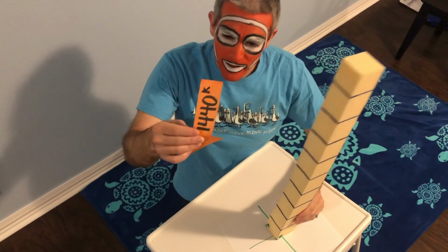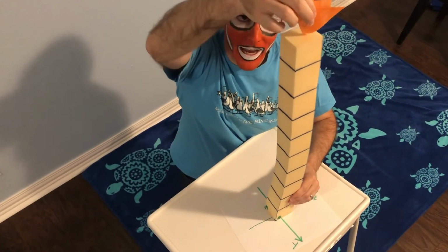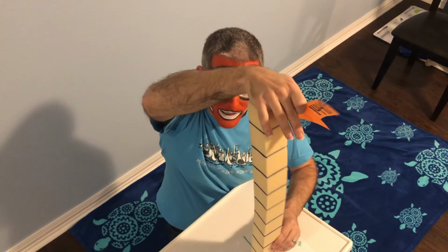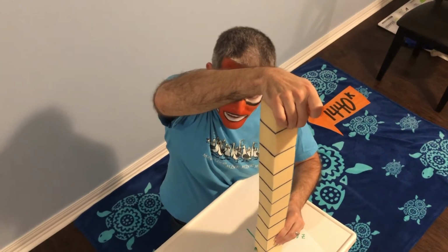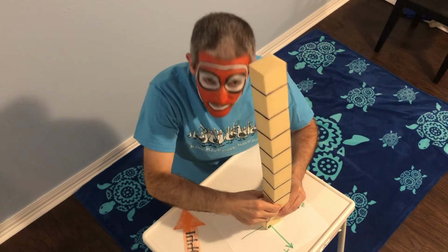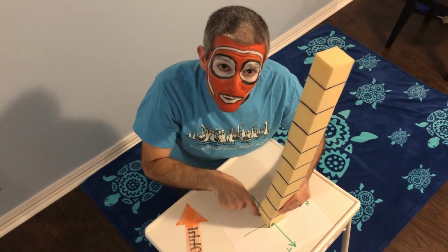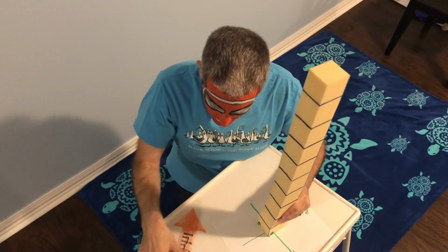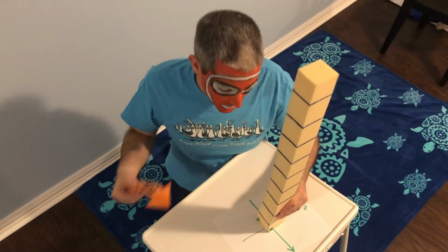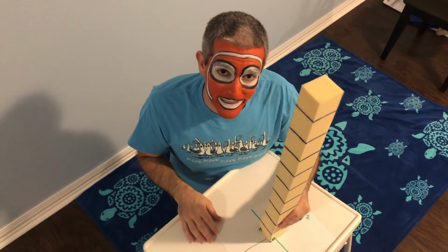So we see the 10-kip force causes compression at A and tension at B. Lastly, we have our big 1440 kip force, and that's acting in the negative x direction. That's just compressing this column, so it acts as a force over our whole column. You can see that force will compress the entire cross-section, and we'll end up with compression at both points A and B due to the 1440 kip load. All right, so that's a physical look at what's happening in this problem. Let's go ahead and finish those calculations.